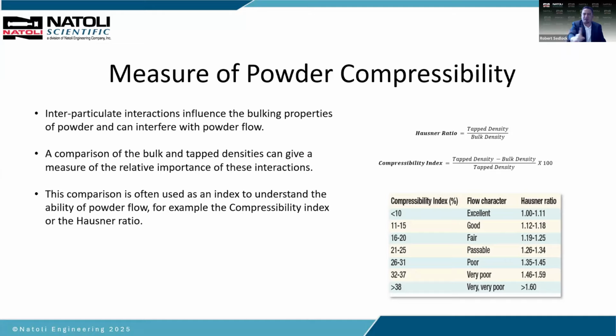You have to slow it maybe to 50% or 30 or 20% to make sure your die has enough time under the feeder for your formula to flow into that die hole. That's called your feeder fill time, typically about 150 milliseconds, 200 milliseconds. That's a very fast time for that die to fly by. So if I slow the turret speed down, I increase the feeder fill time to get that material to flow in there. So poor flowability doesn't mean it won't work. It means you're going to have some challenges.